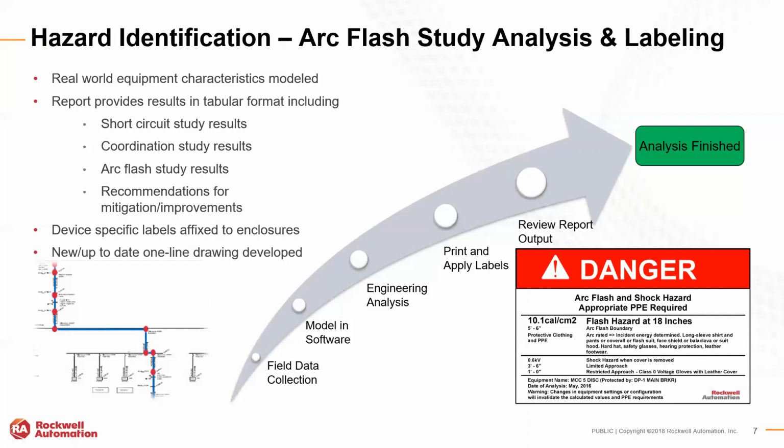There's generally a report also provided. Best practices report usually has a short circuit study included. A short circuit study is performed and basically flags any protective devices that are not adequately rated to handle a short circuit or a fault event. And it will give some recommendations on how you can proactively change those fuses before they may potentially fail.